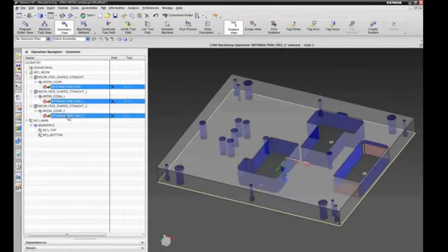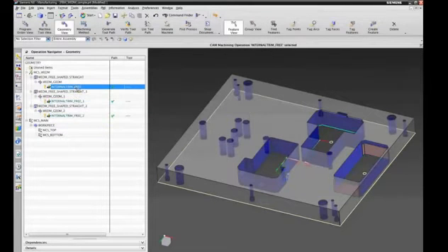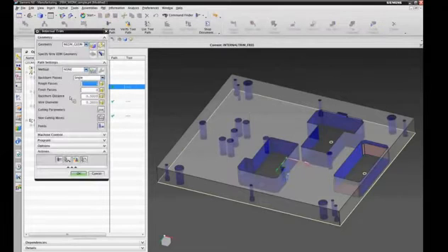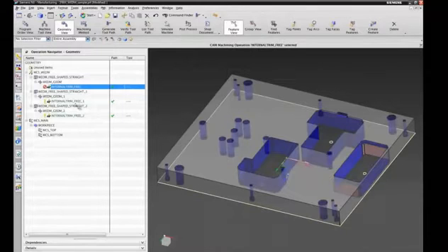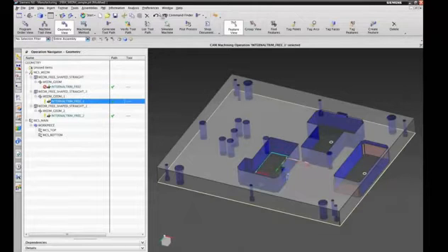And if I generate the tool paths, quickly done, you will see an internal trim operation with a single roughing pass and 3 finishing passes, whatever I want it to be, right? So we can generate that type of operations as well.